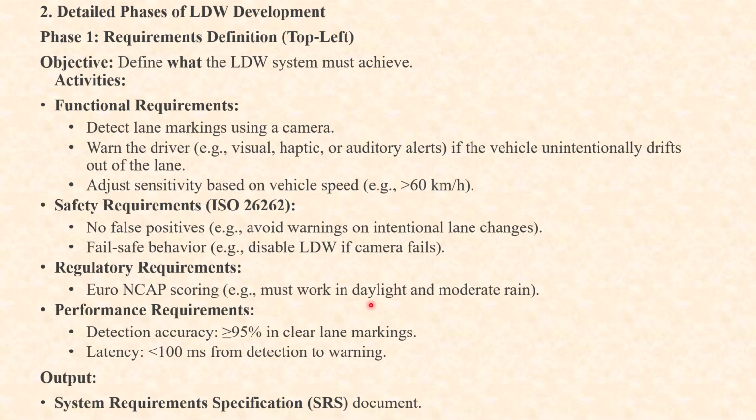All these requirements are clearly outlined. Now next is performance requirements: detection accuracy greater than or equal to 95% in clear lane marking, and latency less than 100 milliseconds from detection to warning. This latency is very important, because the smaller the latency, the better the real time working condition.